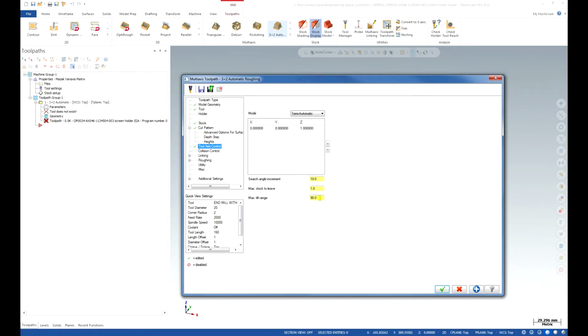But you still have this Mastercam automatic search on top of the tool planes you add. So in this box, you list your tool planes that you tell Mastercam to machine to rough your 3D model. You add and select planes in the same way as you do in manual mode.